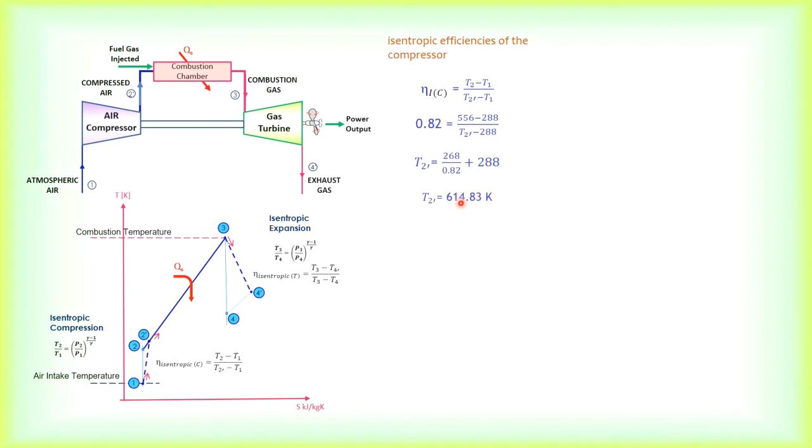On this gas turbine unit cycle, the first thing is to find all the relevant temperatures. If you are using enthalpy, then you will have to find the enthalpies of each of these points. But for the gas side, you won't know what type of gas you are using, so you cannot use a gas table unless they have specified the exhaust gas.